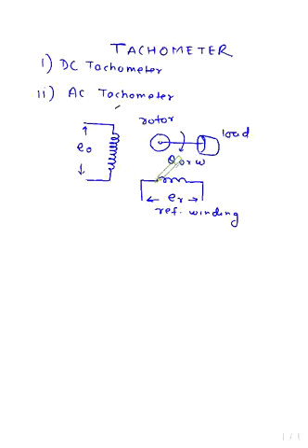These two windings are always connected perpendicular to each other, and one of the windings is excited by a constant voltage. That is known as the reference winding. When the rotor is stationary, the peripheral flux links the reference winding, and as the rotor rotates, the rate of change of flux induces an EMF which is directly proportional to the speed of the rotor. The AC tachometer is also known as the drag cup generator because the rotor shape is a drag cup.